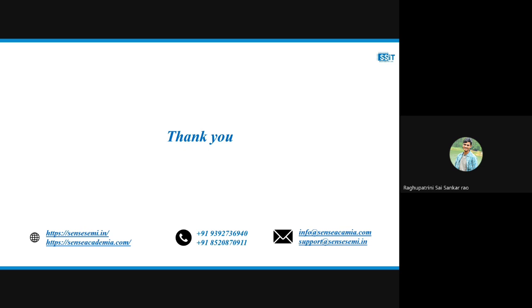If we use multi-layer PCBs also, we can keep components on both sides of the PCB. Even in a double layer, we can keep components on the top layer as well as the bottom layer. And there are hybrid design models also, where we place a few critical components in the middle of the layers, but that is a very rare case. Ideally, a lot of PCBs place components on the top layer and bottom layer. Good session, sir. Thank you.